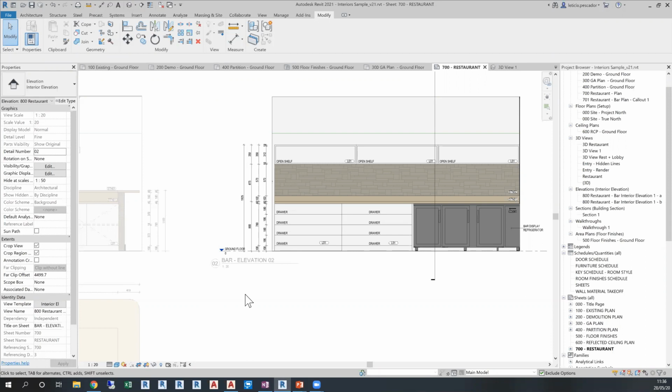There are ways we can bring AutoCAD drawings in to start families, but ideally we will rebuild that family within Revit with Revit line work and Revit geometry, especially if you're going to need to create parametric relationships, assign materials, etc. If it's just a 2D component, you could get the outline and use that as a placeholder to begin with in Revit.